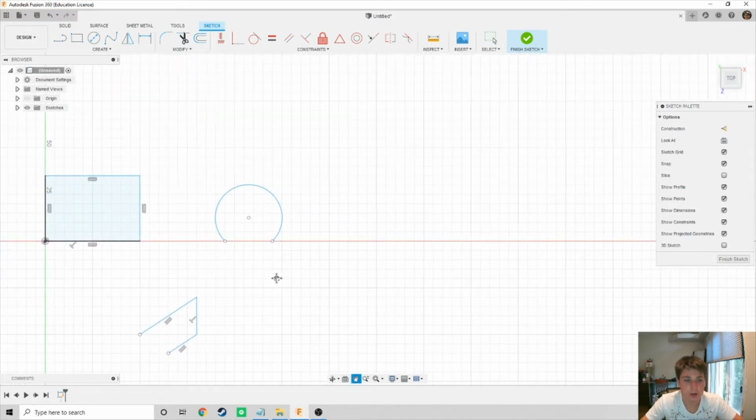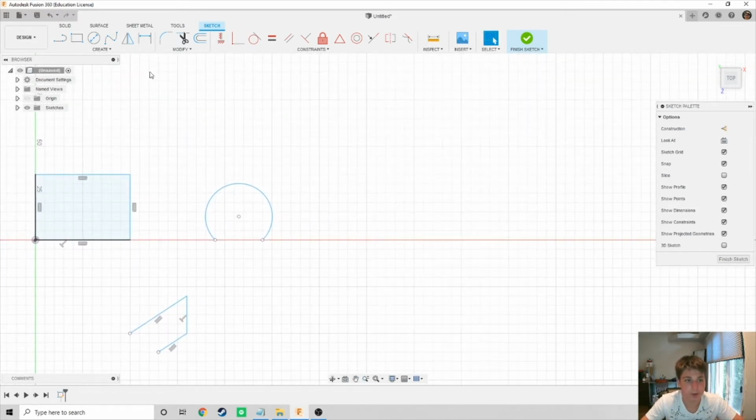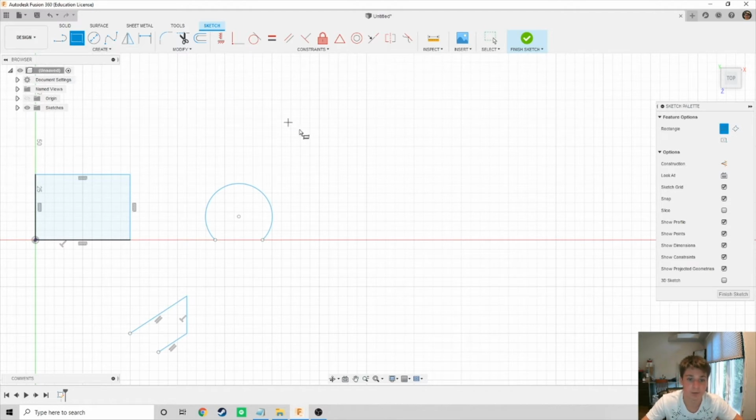When drawing your 2-dimensional sketches, we have the ability to dimension our sketches to be precise, whether that be during drawing the shape or after the fact. And I'm going to show you an example of both. I'm going to use my shortcut R to get the 2-point rectangle, and I'm going to start with a very simple 2-3 click method. I'm going to start with my first click, and I'm going to start expanding my rectangle. I haven't done my second click yet because I'm not going to.